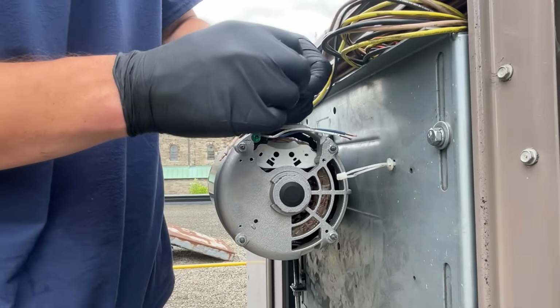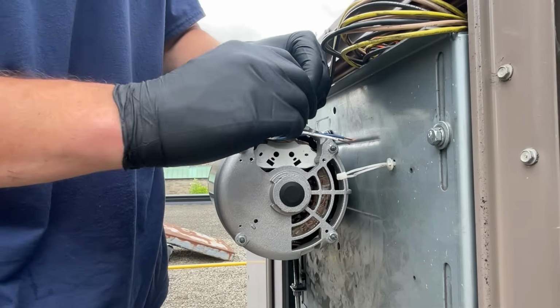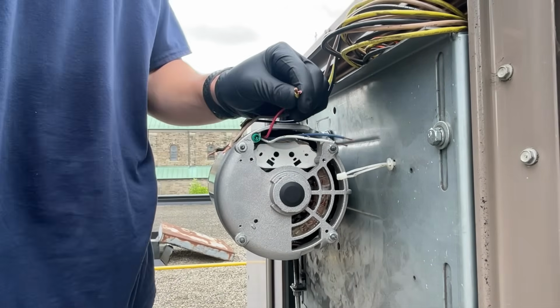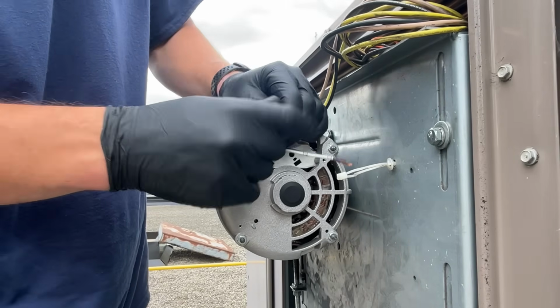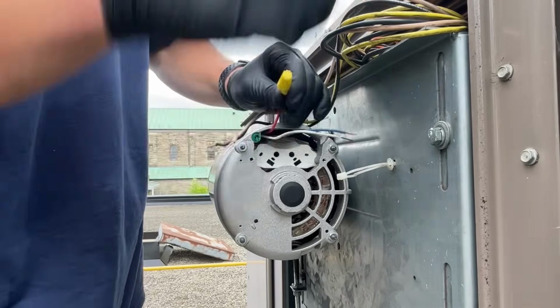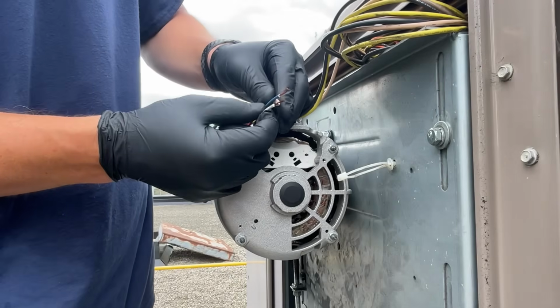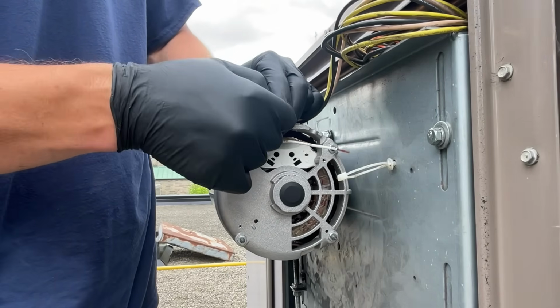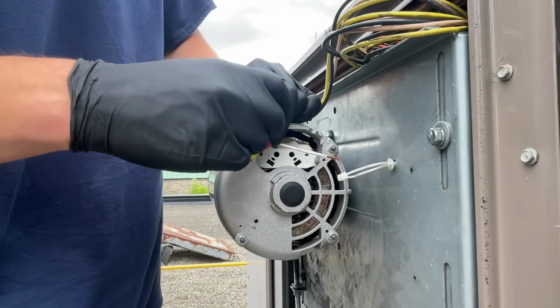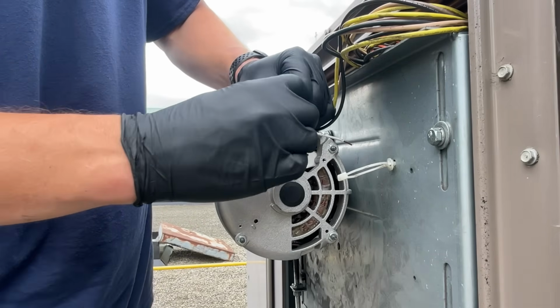We've got our motor plate electrical cover removed. Now our aftermarket motor doesn't have spade connectors or terminals like our old one did. That's fine. We'll just use wire nuts here. So these 3 lines here, L1, L2, L3, will go into L1, L2, L3 on the motor.